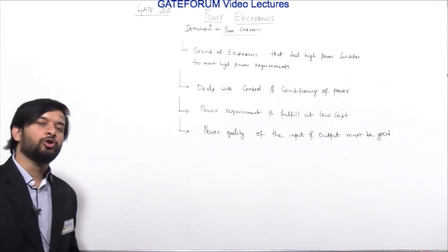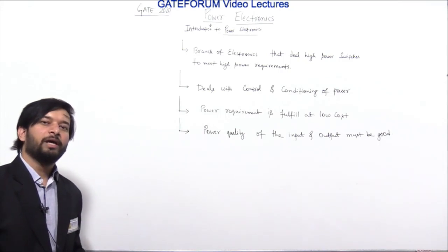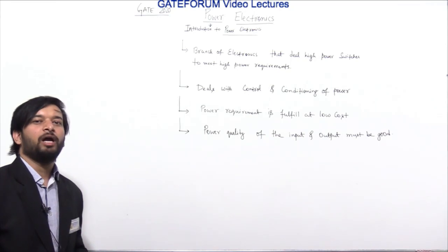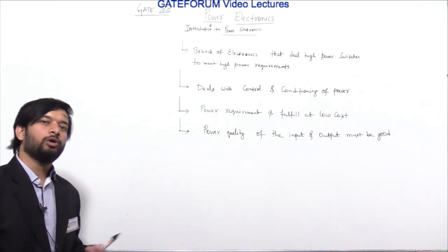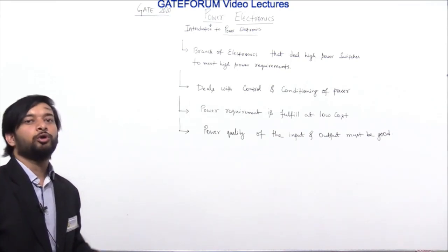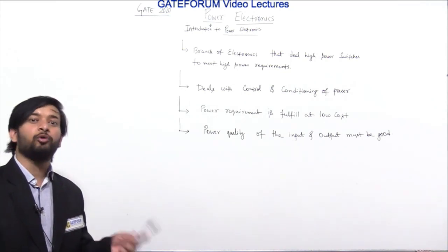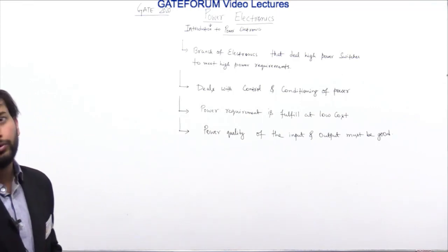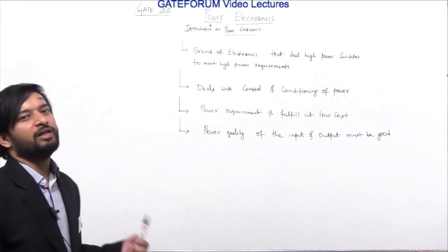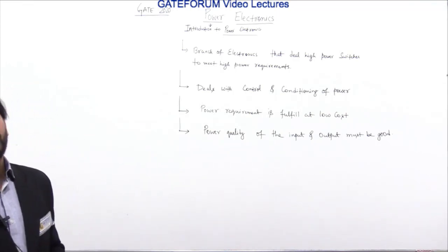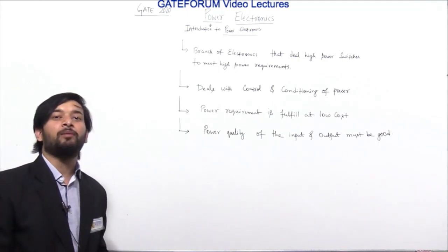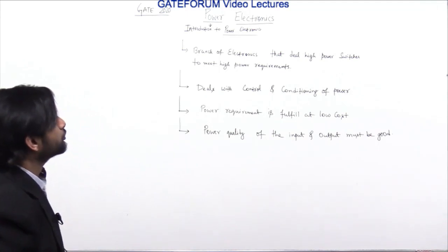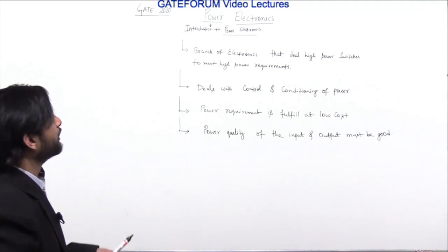Total harmonic distortion. When you are using AC supply, you'll have total harmonic distortion in the waveform, which is used to see what content of harmonics or undesirable components are present in AC. And when you are dealing with DC, you'll be using ripple factor to see what content of harmonics is present in the DC supply, or DC output. So all these will be used to analyze.